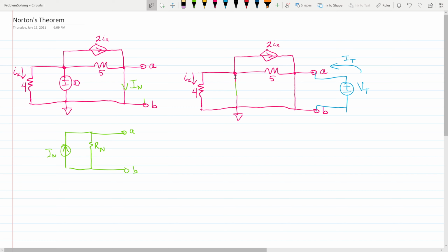And you might be able to do that, of course, using mesh analysis or nodal analysis. In this case, it would be smarter to use nodal analysis because there are only two independent nodes. So that would be the wise choice here, versus 4 equations if you were to do mesh analysis. So you do nodal analysis here at these two nodes, 1 and 2. You'll solve for IT, and you know what VT is because you're the one supplying VT, so you can make this an arbitrary voltage if you want, make it 1 volt.